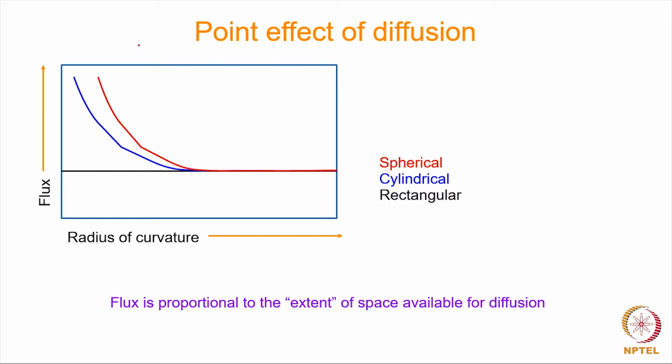So by estimating the temperature at which the process is happening, and then the diffusivity relevant at that particular temperature, and then the diffusion length in that scenario, you can see whether the radius of curvature is large or not. Accordingly, we can pick the geometries. If the radius of curvature happens to be very small, then we will be forced to choose it to be cylindrical or spherical as the problem requires us to.